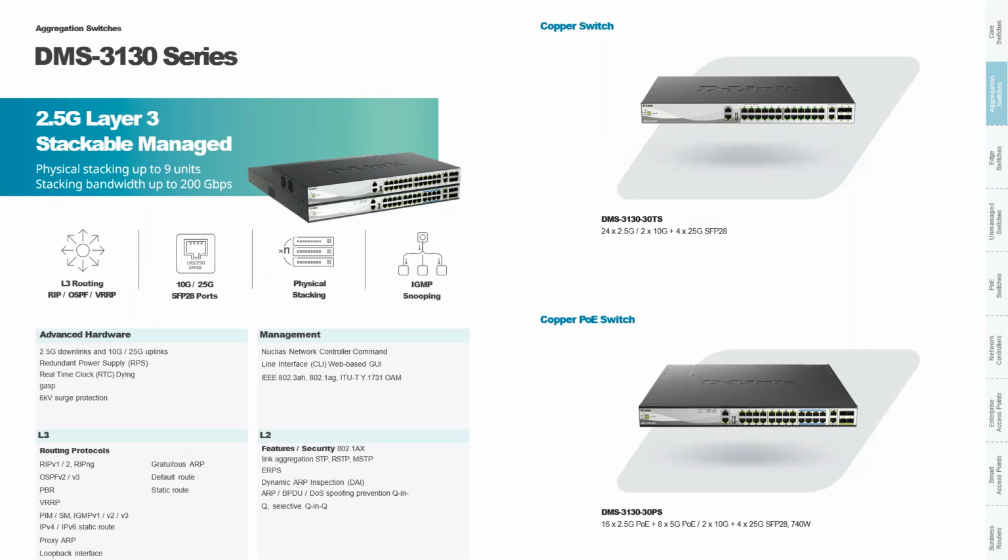Just to come back on that PoE point, 740 is the standard, and with dual power supplies you can get up to 960 watts. So you can get some serious power out of this base. Yeah, it does support PoE++, so the 802.3bt standard. That means there's a lot of power through a port, and you can power larger devices, whether it's larger CCTV cameras with heating elements or other options that are needed.